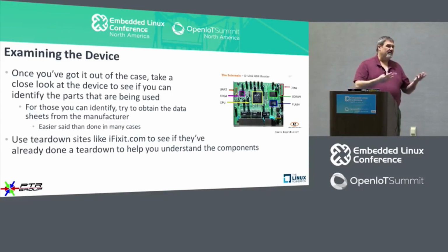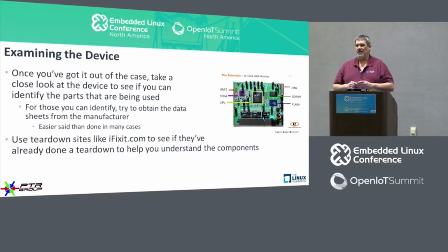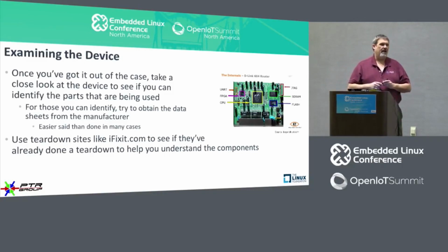So being able to read the part numbers is easier said than done. But if you can identify the part numbers, try to get a hold of the data sheets. In some cases, the manufacturers will be more than happy to give you the data sheet. Marvell will give you a data sheet, or Atmel or one of those guys will give you a data sheet. Others, not so keen on giving data sheets.